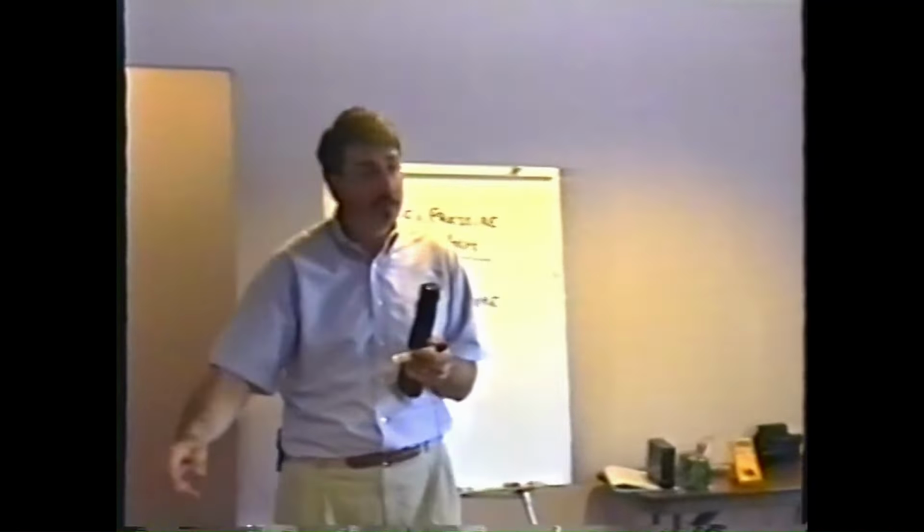Well, all it really means is that this third band tells you the number of zeros to put after the first 2 digits. In other words, it's telling you to multiply times 10, add 1 zero. 100, add 2 zeros. Multiply by 1,000, add 3 zeros, and so on.